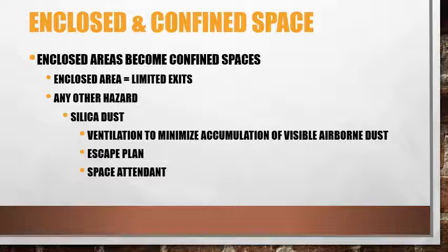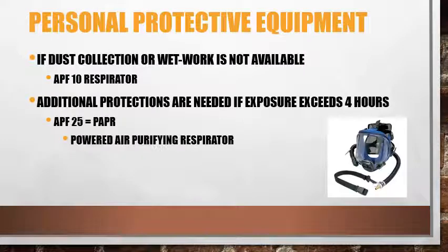So in those cases where you are in a space with limited exits and you're working with silica dust, you need to have ventilation to minimize the accumulation of visible airborne dust. You also need to have an escape plan if the dust becomes too much for you to see or breathe, so that you can get out quickly. You also need to have a space attendant. A space attendant is simply someone outside of the enclosed or confined space who knows you are there, who can rescue you from that situation if you are incapacitated.